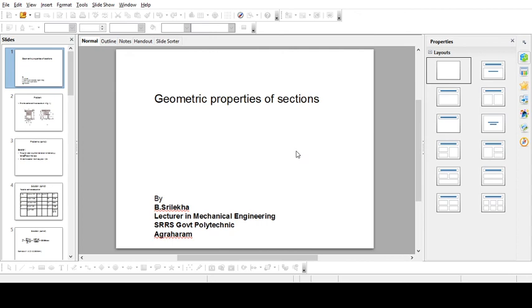Now the y term is 38.2. We know that h by 3 into (2a plus b) by (a plus b) is the formula for the centroid of a trapezium, so you'll get a value of 38.2 there. Now a2 y2 is equal to minus 4,86,000.